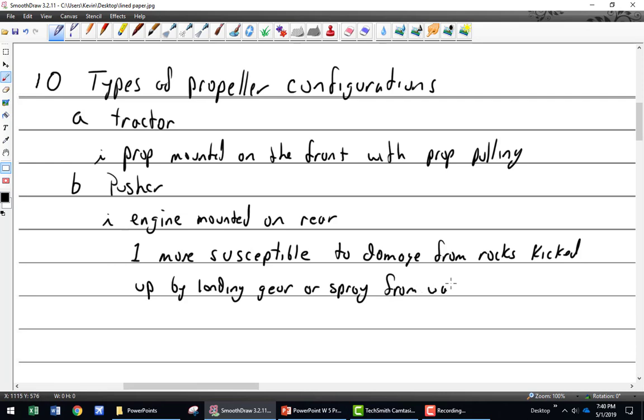On the 337, the rear propeller, is it less efficient because it's getting this air kind of messed up from the front propeller? You know, it's funny. I would think that it would be, but from the looks of it, the propeller is actually smaller. Not necessarily the interference between the two, but more the interference of the airflow going over the airframe. You can get resonance between the two, just like with any other twin, and we'll talk about this much later. The newer models had synchronizers and synchrophasers on them, so you can actually time the propellers to be at a certain spot. Doesn't that mostly create noise though? It's just noise. That's a result.